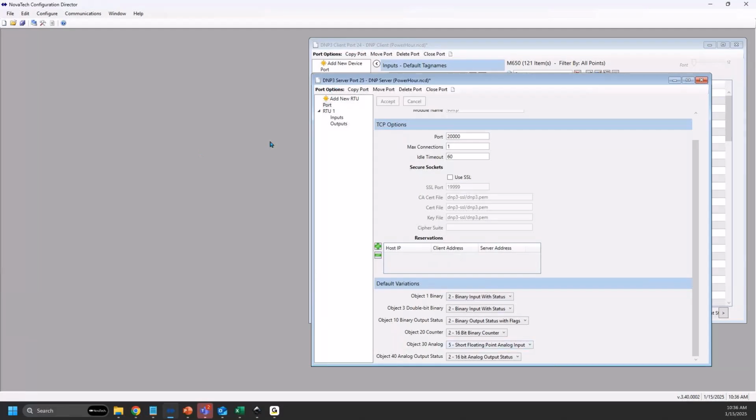If you're using Modbus, when you're configuring each point, you can set each point as an integer, various sizes of integer, or floating point. So just so you know that. Now, in the case of this DNP server, you have to select that, and you also have to know that your SCADA master will support receiving floating point values, because some do not. We're assuming in this example that it does. So that is step one.